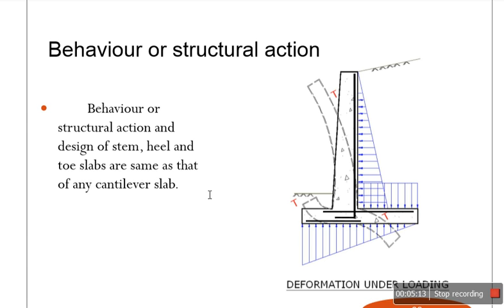If you want to introduce the steel, normally this is advanced concrete design, where the only two materials which we talk about in this subject are concrete and steel. In your retaining wall, normally we provide steel where tension occurs and we ignore the steel in compression, because concrete is very good in compression. If you still provide steel in the compression zone also, you're not exercising good judgment on economy.